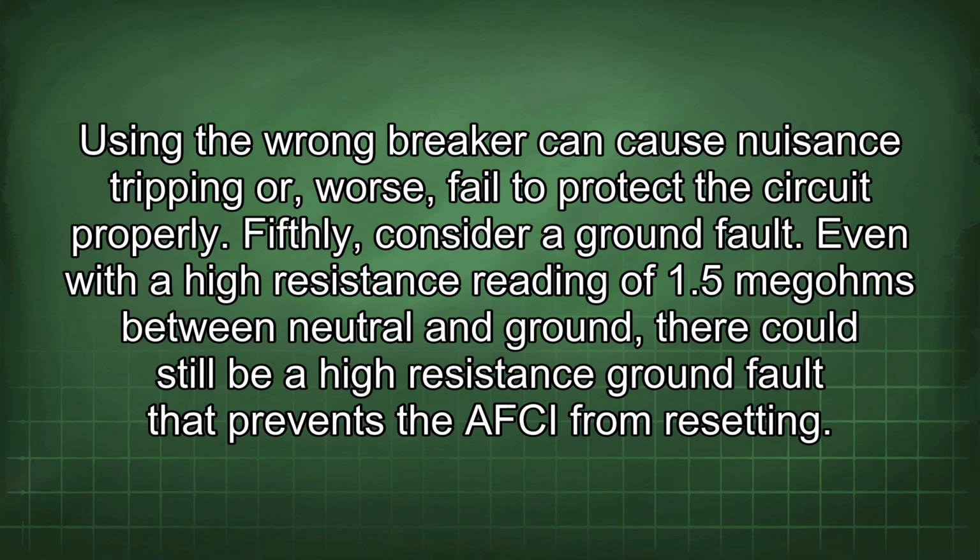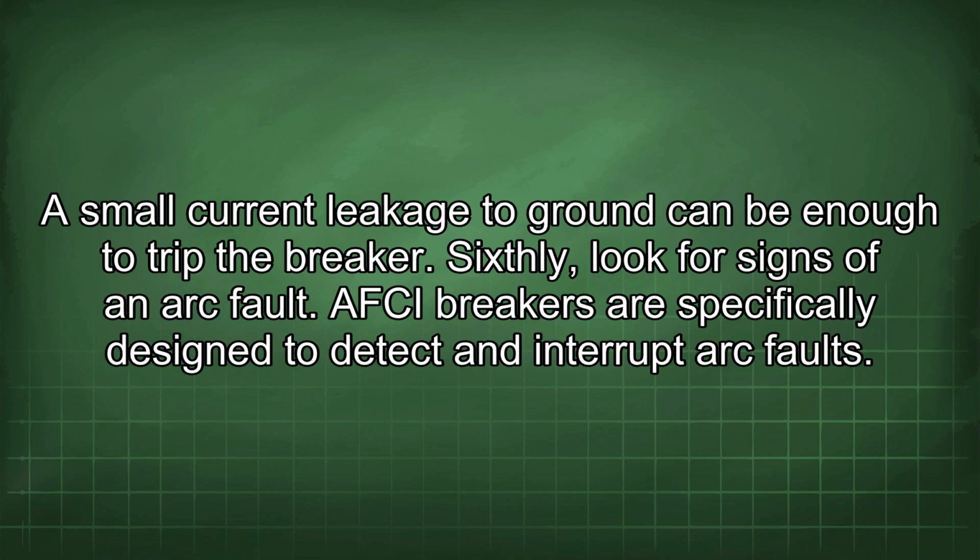Fifthly, consider a ground fault. Even with a high resistance reading of 1.5 megohms between neutral and ground, there could still be a high resistance ground fault that prevents the AFCI from resetting. A small current leakage to ground can be enough to trip the breaker.